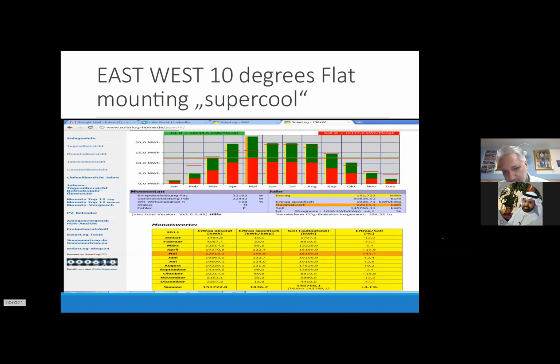So between April towards September, October, you can see the high output of this system, because in summertime it's expected to be less in the old data logging equipment from the Solar-Log, but it was outperforming because it's colder and has a higher voltage than expected. And of course, in January, February, where the angle is steeper in Germany, it loses out a little bit again. But overall, it's like 4 or 5% more efficient.